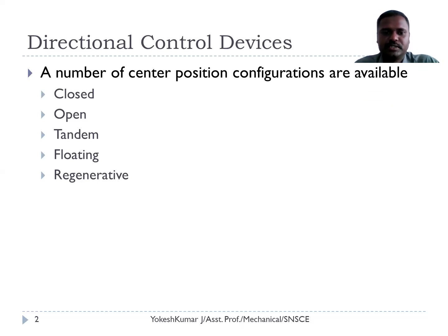The first position is closed. Second is open. Third is tandem center. Fourth is floating center. Fifth is regenerative center. Each one of these cases has its own applications, and we have to discuss the symbols and their applications.